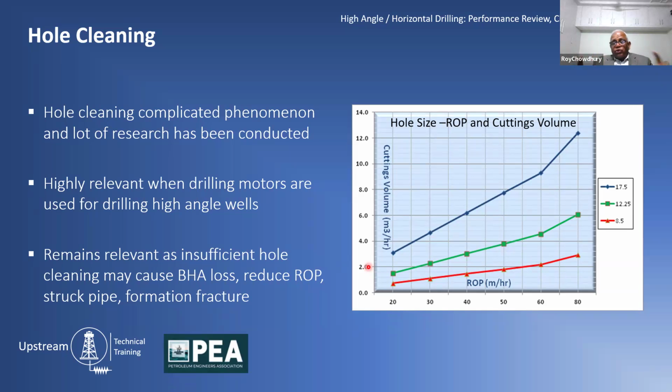Of course, if these cuttings do not escape the hole, they will settle down on top of the stabilizer. They will make a cuttings bed maybe, and they may cause stuck pipe. They may even fracture the formation. I'm sure many of you have seen it in your career.